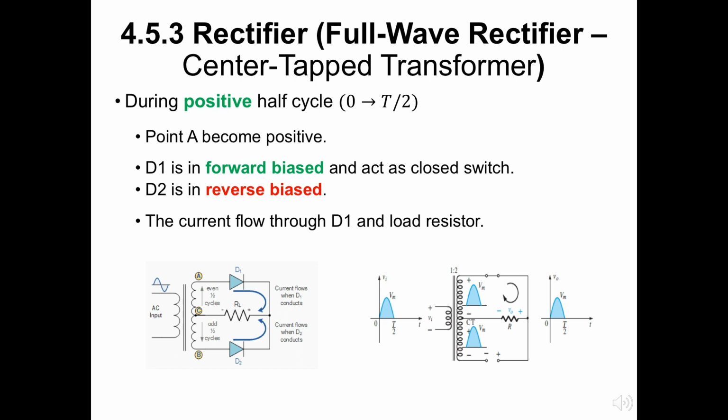During the positive portion of VI applied to the primary of the transformer, the network will appear as shown in right figure with a positive pulse across each section of the secondary coil. D1 assumes the short circuit equivalent and D2 the open circuit equivalent, as determined by the secondary voltages and the resulting current directions. The output voltage appears as shown in the figure.